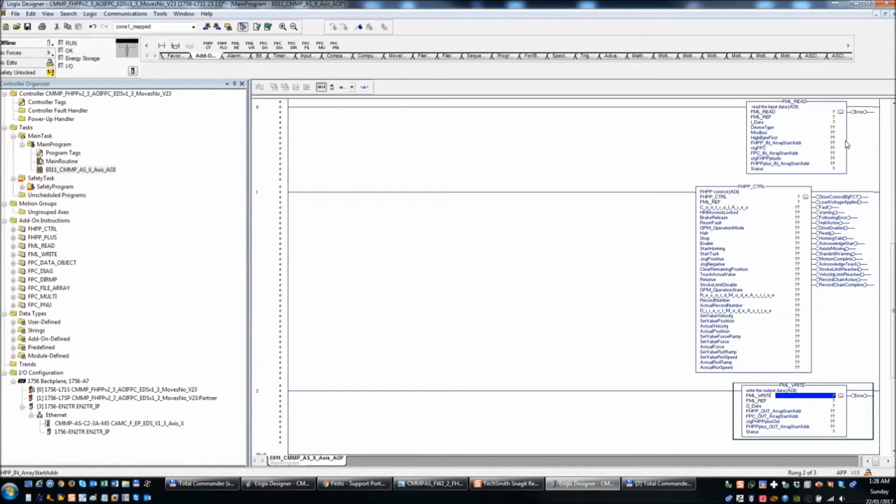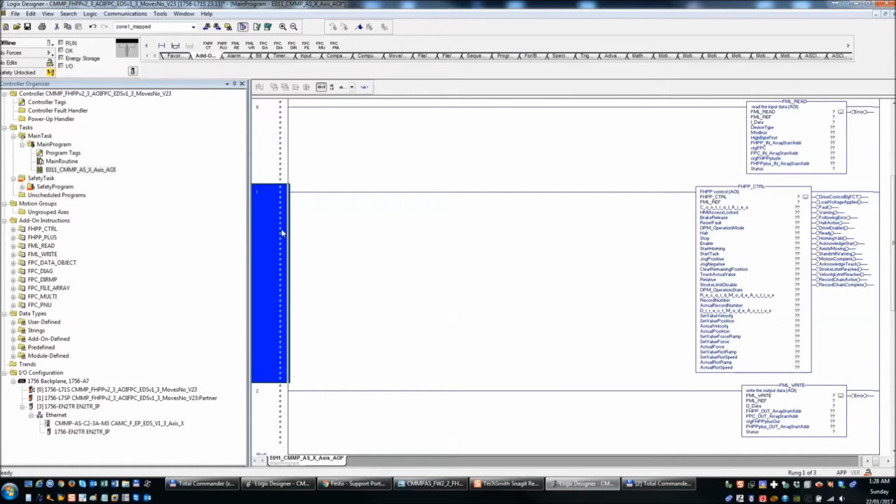And like any PLC, you do a read, execute code, and then do a write. So the write's always the last thing, the read's always the first thing. All of these instructions, they need to be scanned all the time. So don't put any code on these lines here, leave them on. The only code that should be here on these lines will be communication steps. So you don't want to play with code over here, just like in normal cases, if you're not communicating to the device.